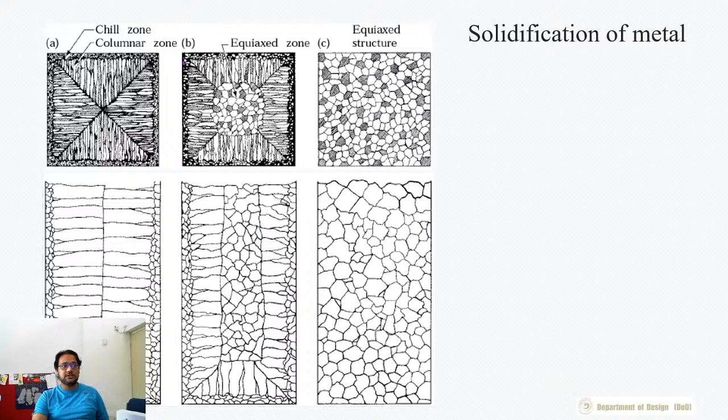Okay, as you can see in this cross section, this small section at the center has larger grain structures, and that can be seen in this cross section area also. So these two give you an idea of, if we have a material which is casted, when it is cooled down, what is the arrangement of grains internally, and this becomes very important for us to know about the strength of that casted part. Okay, and this is one of the things that you need to control when you are designing for casting.